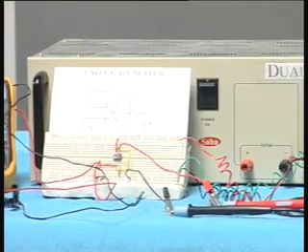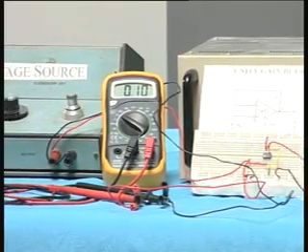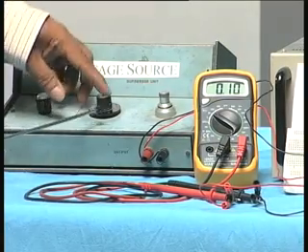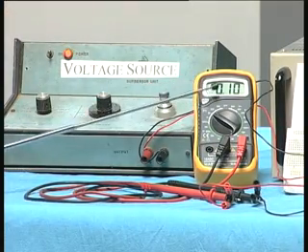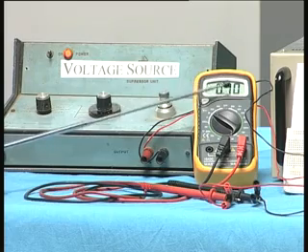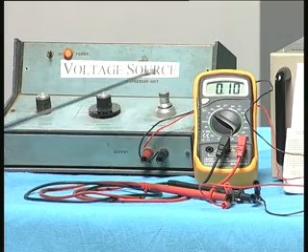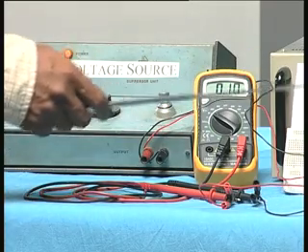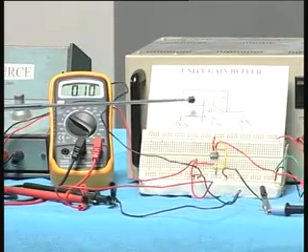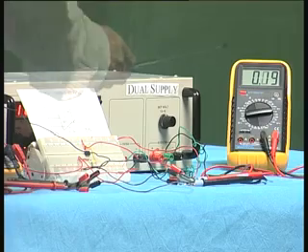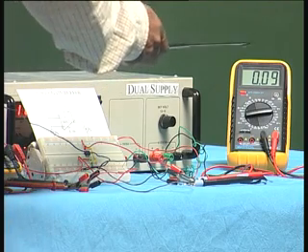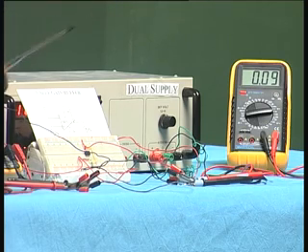Now what I have done is I have given 100 millivolts. This is in the 100 millivolt position, so I am giving 100 millivolts, which is read by this multimeter as 0.10 volts, which is correct. 100 millivolts is 0.1 volt. So what should be the output? Because there is no R1 R2, the feedback is complete, 100%, therefore the output is the same as that, right. So it is 0.09 instead of 0.1, because it is not exactly the same as the input, slightly less.